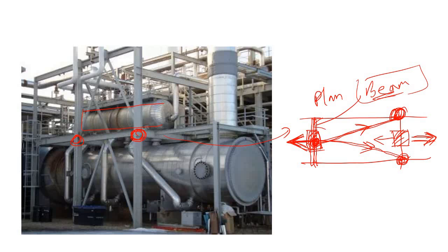Now if you come to this elevation, we now have lateral load here and here. This is the support. So to transfer this lateral load, we simply have to put another vertical bracing like this, and that is the reason you can see this is the vertical bracing we have put. Clear?